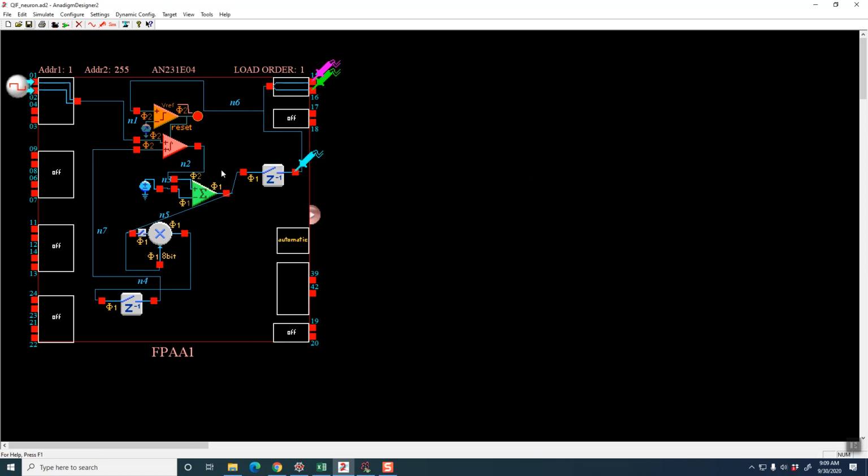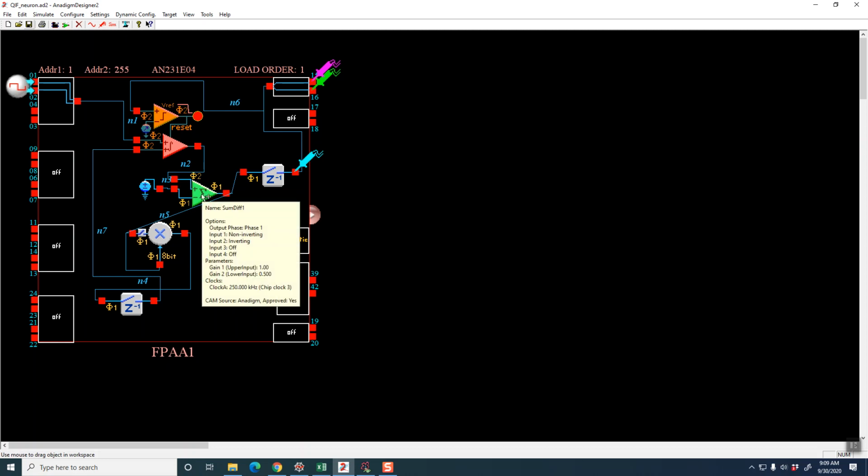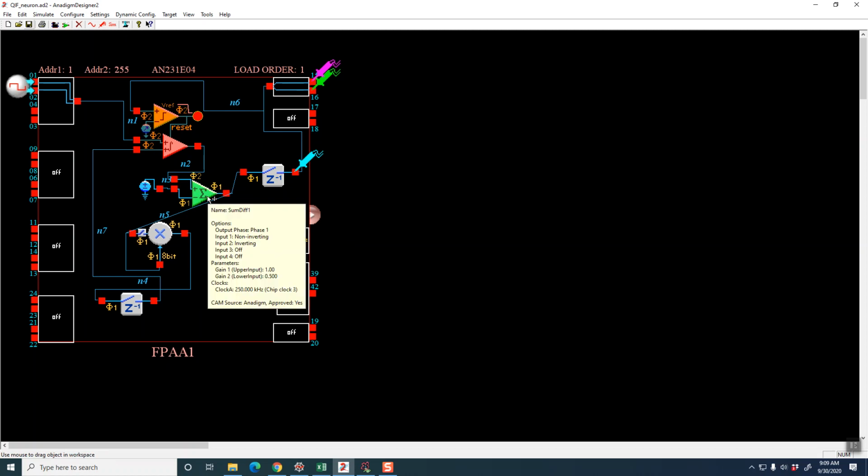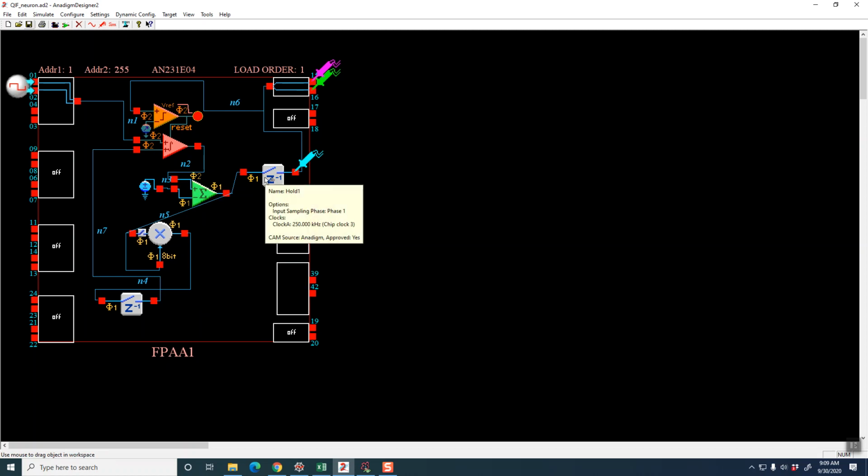All right. Then this is actually how you add in the reset voltage. Because if this resets and this goes to 0, then you add in whatever is here, right? Now these summers are half cycles, so in order to see the output, you've got to put a sample and hold.